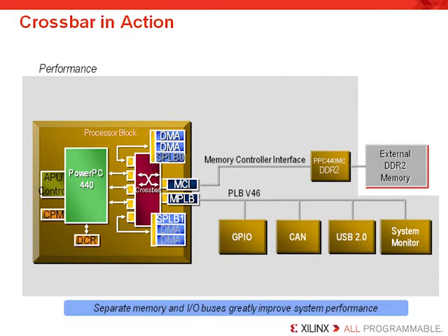The memory is connected to the memory controller interface bus and is connected to the DDR2 memory controller, and this is connected off-chip to a DDR2 memory. In this case, there is one master device, and that's the PowerPC 440 core, and it can access any of these peripherals. So again, fewer masters, relatively simple system.